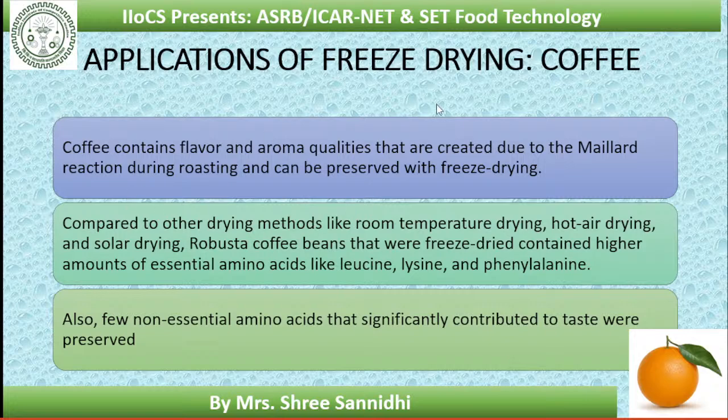Let us see the application of freeze drying in the coffee industry. Coffee contains flavor and aroma qualities that are created due to the Maillard reaction during roasting, and can be preserved with freeze drying.